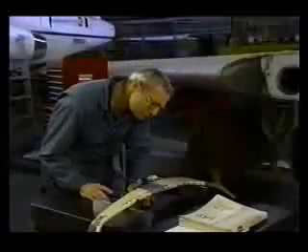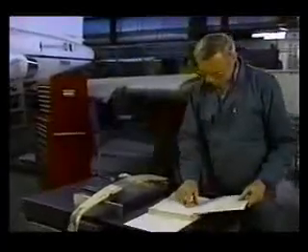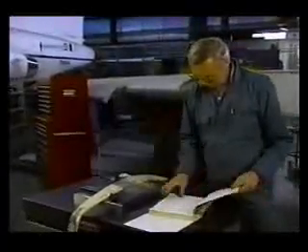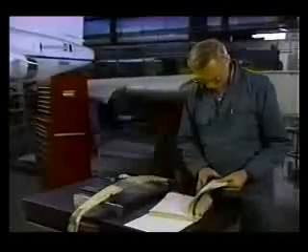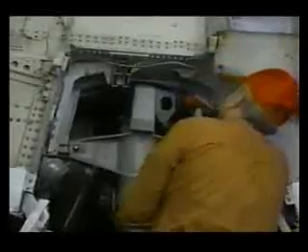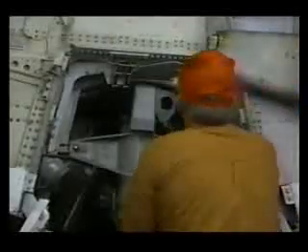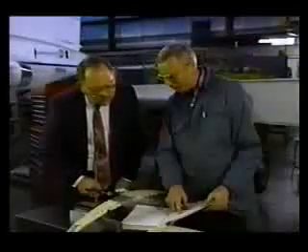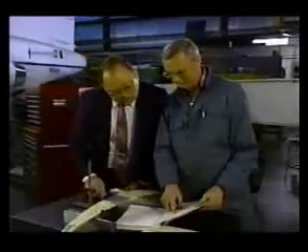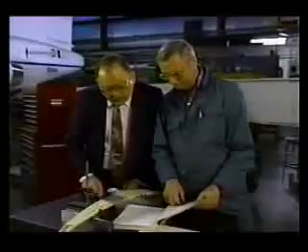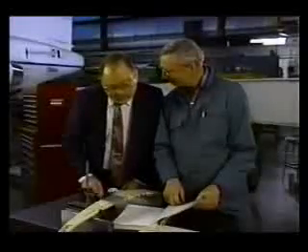Now that you have measured the extent of the corrosion damage, you must compare this last figure with the manufacturer's predetermined acceptable rework limits. If the damage exceeds the limit set by the aircraft manufacturer, the affected parts must be replaced. On large structural parts, where the corrosion damage exceeds what is allowed in the structural repair manual and replacement isn't practical, contact the aircraft manufacturer. Corrosion damage not outlined in the aircraft structural repair manual will require FAA engineering or manufacturer's data to repair the component.